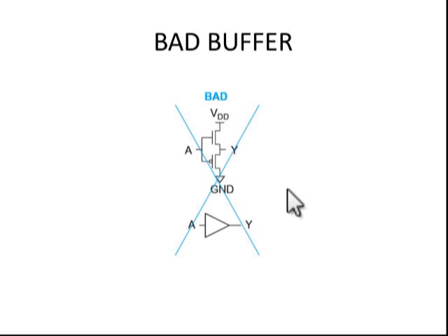But if we use a pass transistor and transmission gate, I am getting some intermediate outputs. So to avoid these things, we are going for the CMOS because CMOS gives only two values, either 0 or 1. Okay, 0 or VDD in analog. So that's why we are going for the CMOS.